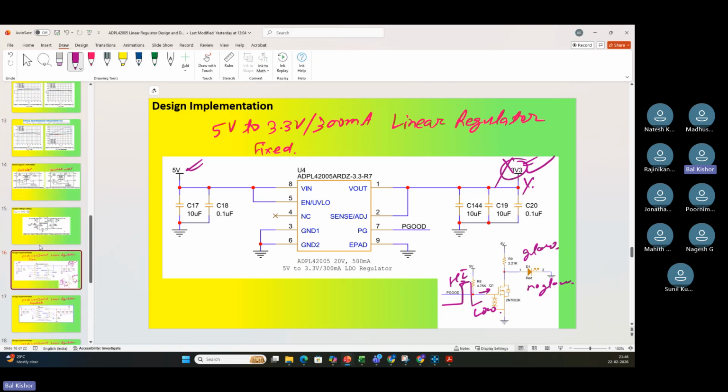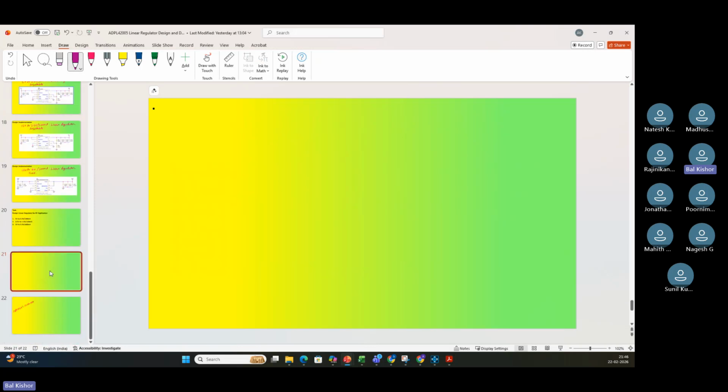I think yesterday I had explained everything, but you were not there. Let's do that quickly. If you see the block diagram in the data sheet, you will see that the power good pin is like this. This is my PG pin, and this is, let's say, the boundary of my IC. This is connected to ground, and here your feedback pin is coming, which is driving the gate. So this MOSFET is inside the IC, and this is my PG pin, which is outside the IC.